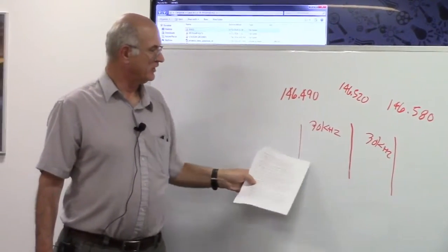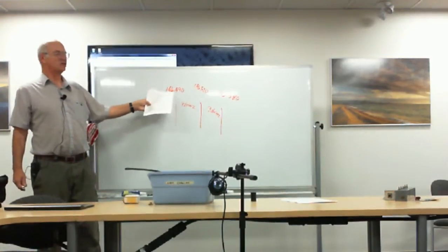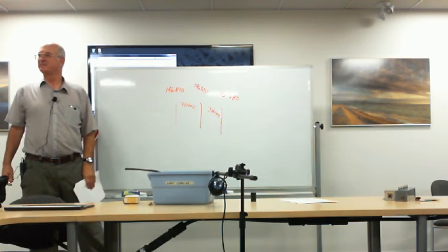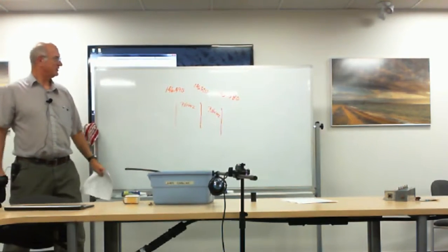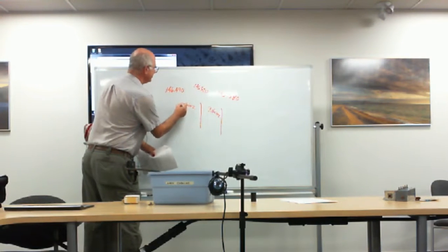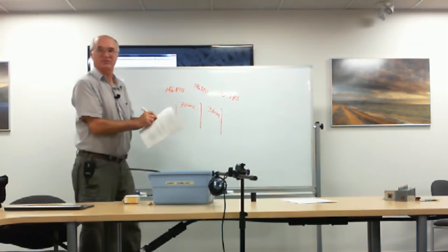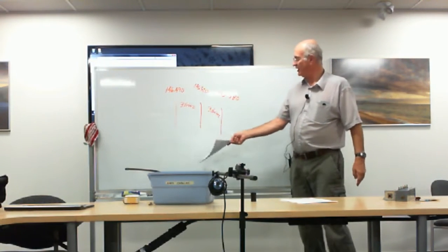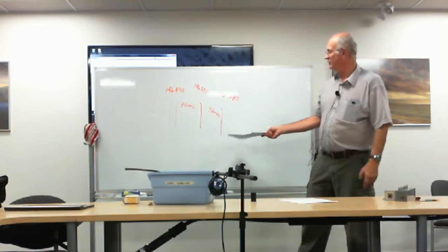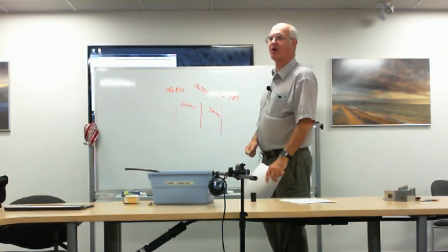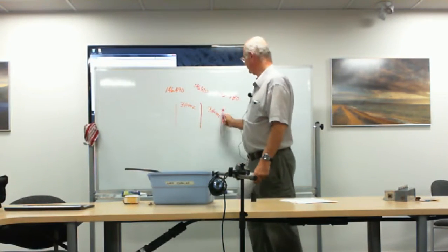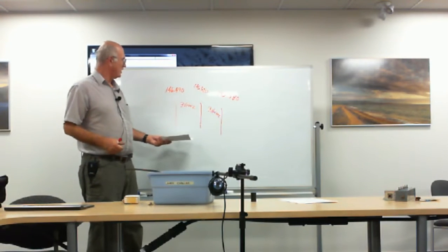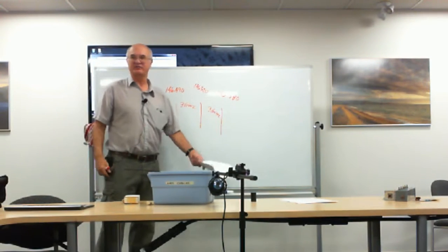That's because these are 30 kilohertz apart. And if you do the math, one of the calculations of sum the difference in the two originals is always going to generate this one. Sorry, I must get lost. I thought it was 7. No, 30s. Sorry, 30. This is the most common effect, and these can be any distance apart, as long as they're uniform. So this is your standard two frequency, third order intermod. Two frequencies, third order. Can go either way. This is the most common, and if we had a couple of radios, we could demonstrate it right here, right now. It's very easy to do.